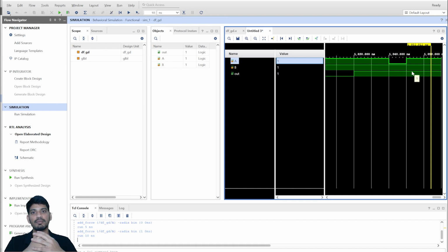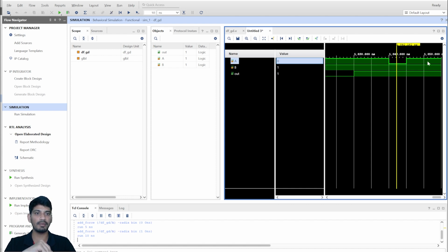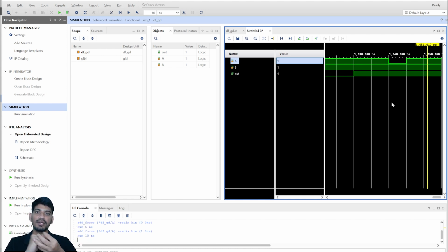This should be very clear because this will be very helpful to eliminate the glitches inside your circuit. The glitches are nothing but the short pulses that are appearing in inputs. So we can eliminate those glitches like this. I don't want to have this data, so I eliminated it by giving a larger delay to my expression compared to the pulse width of my input. This is a very important topic while you are designing real world applications.